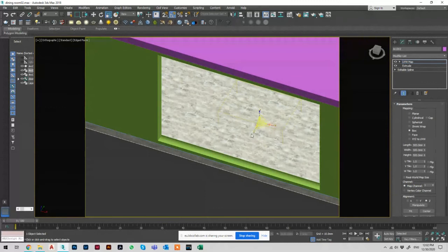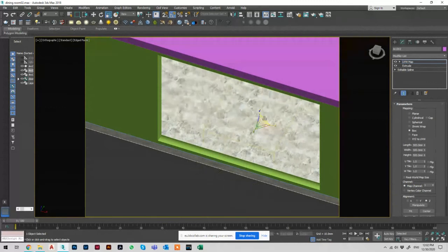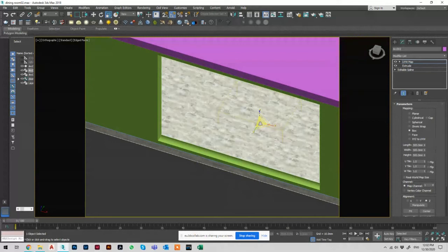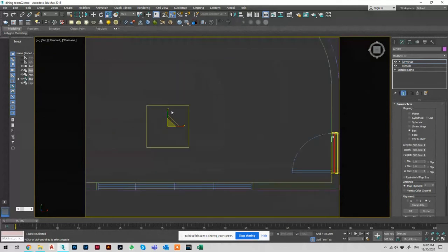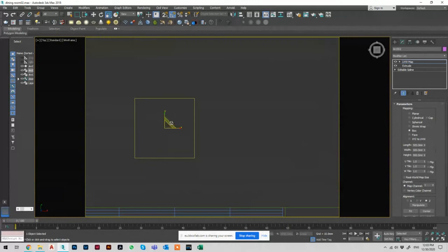You can use the X-axis only. You can use the Y-axis only, you can use X and Y, and then you can use all three together. Make sure that you know the difference, because for example, if you're in the top view and you select these only, it will change the X and Y without the Z-axis, either for a UVW map or for blocks or for anything. Some of the students are just using these two for the blocks, and this will create some issues. Some of you are using just the X-axis, some of you just the Y-axis, without knowing that you really need this. So just make sure to know: if the axis only is yellow, this means that you're selecting the X-axis only. If the area between these two is yellow, this means that this is X and Y. But if you have this triangle, this means X, Y, and Z all together.